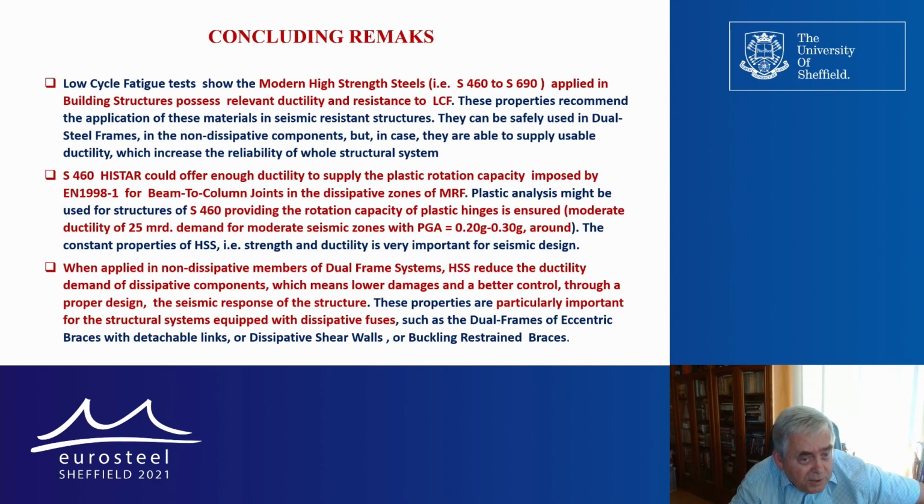Also, 460 provides the rotation capacity of plastic hinges, which can be ensured in order to fulfill the moderate ductility demand in the code, which is 25 milliradians, and apply in these conditions in a very good safety environment for moderate earthquake, 0.20 up to 0.30 g.